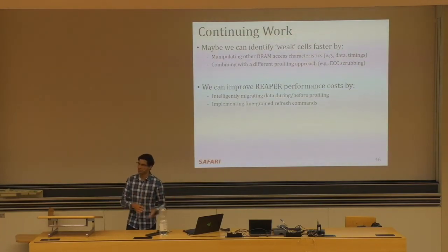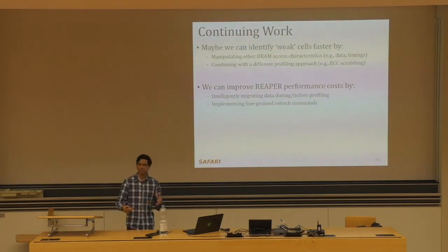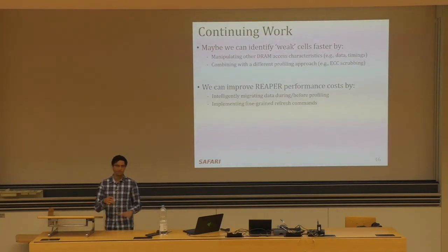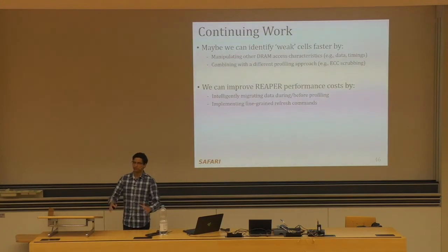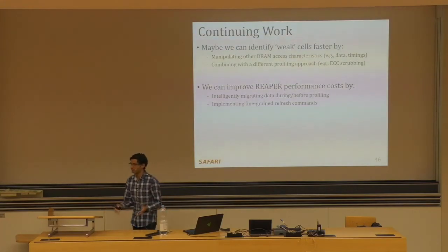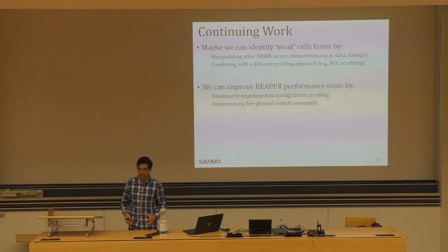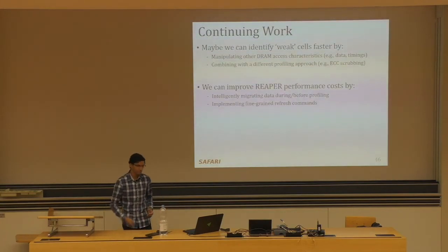Some really older generation DRAM devices actually did have something like this. In today's devices, the refresh is a very highly optimized process, and you have very limited control over it, which is why you can only refresh a rank or, at best, a bank at a time. But in research, we're free to propose whatever we want, right? And so if we propose some sort of intelligent mechanism to have a more fine-grained refresh command, we can start profiling small pieces of the DRAM at a time, as opposed to just having to do everything in one shot.